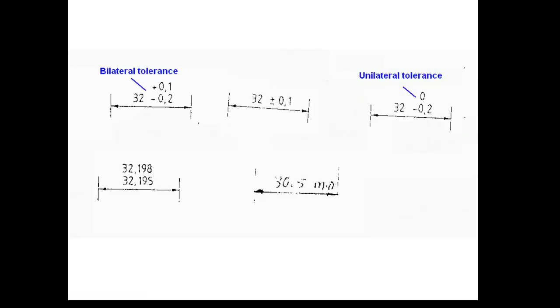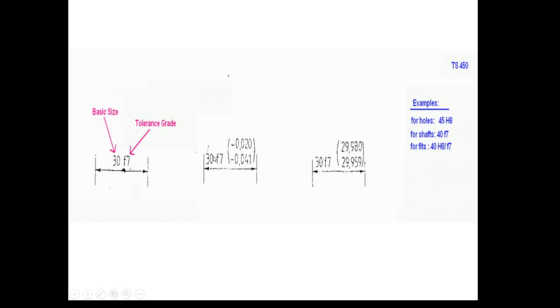So, obeying this rule, see, the deviation for 30 starts from hundredths. The other deviation also starts from hundredths. Since both of the deviations, or at least one of them, start not from tenths but hundredths, this dimension is wrongly indicated.